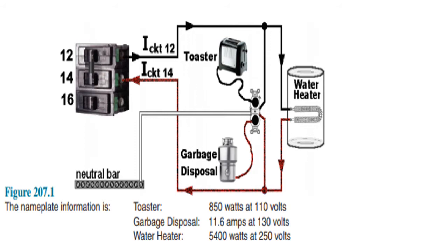Well, let's look at this together. First and foremost, what do we need to determine? We need to determine the fixed resistance of every load involved. So let's go ahead and calculate using their overall ratings and their rated voltages before we apply any other voltage to them. After we've calculated using all those Ohm's law formulas, we can determine their fixed resistance per equipment listed here below.